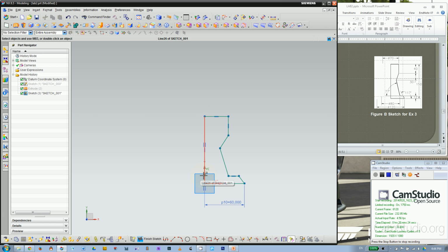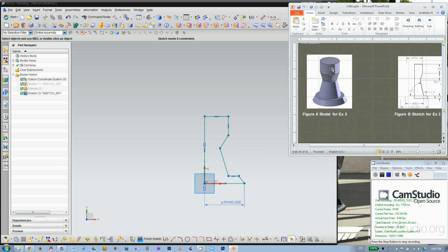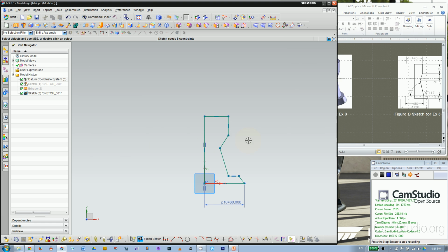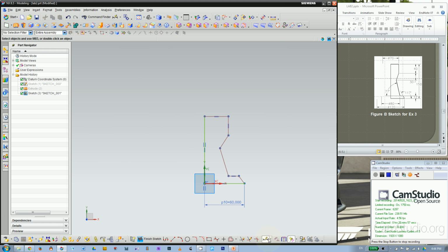And that's another topic about how to position your coordinate system. You have the rotation axis right in the middle. So you want one axis to be your rotation axis. If your sketch is like this, it's okay, but it's not very professional looking. Okay, so I'm gonna put this line in the middle, then keep adding dimensions. So some of the tricky dimensions are maybe 12.